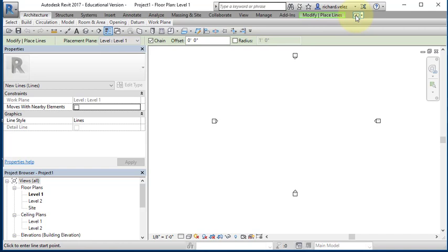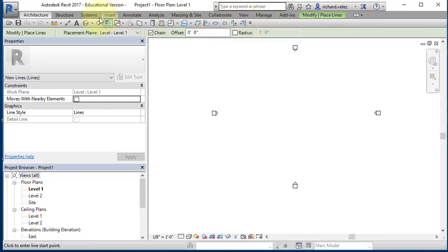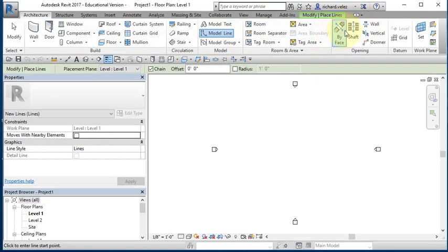And if I select this again, it disappears altogether, and all you see are the tabs of the ribbons and my quick access toolbar. If you ever open up Revit and your ribbon is gone, simply come up here and select and toggle through, and selecting it one more time will open up your ribbon. And this is the preferred view where all the commands are visible. So as I said, you'll be in this architecture tab 90% of the time. One of the commands you're going to need to access is in the View ribbon.